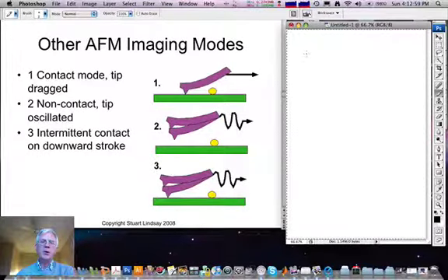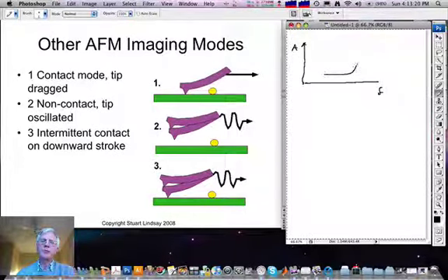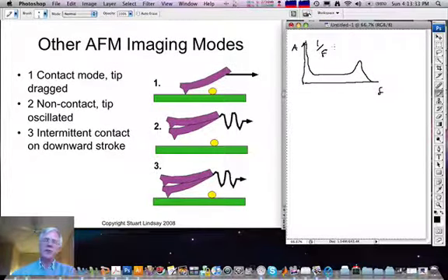And the idea here was, first of all, of course, to interact less with the surface, but also to achieve a particularly sensitive form of detection. Because if you remember, when we talked about the response of a cantilever as a function of frequency, so here's the resonance of the cantilever, I pointed out that at low frequency there was always this contribution of very large noise, so-called 1/f noise, which comes from the weak mechanical components in the circuit.